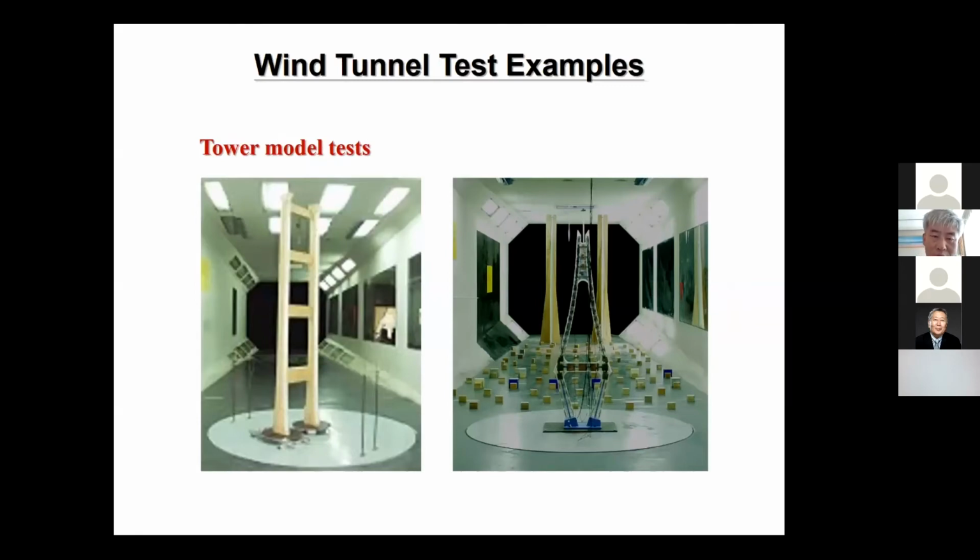So for the bridge side, we also have here just some tower model tests. We also do some even elastic models for the tower models, because currently for the long span bridges, the towers of the bridge are several hundred meters high. So they are now very slender high-rise buildings.